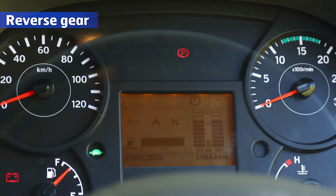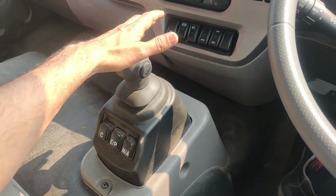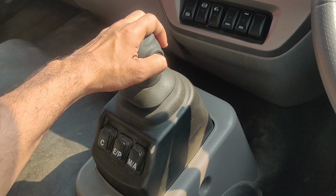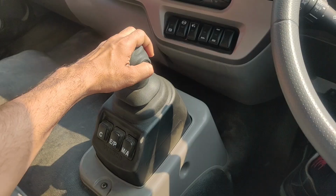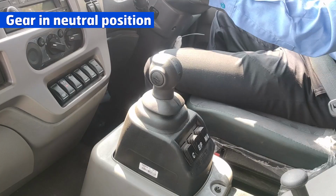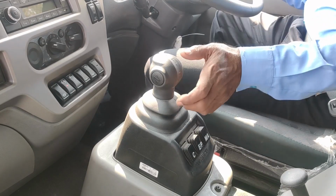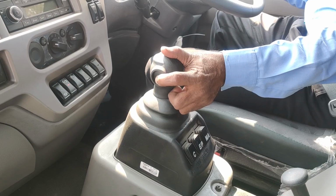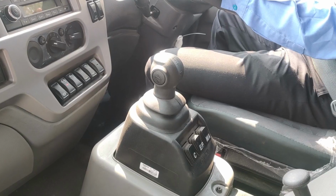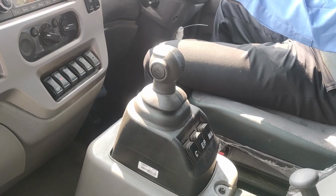Reverse gear. When the gear is in neutral, reverse gear is requested by pressing the function button of the shift lever unit and simultaneously moving the shift lever backward. Gear in neutral position. A shift to neutral is requested by pressing the neutral button while the function button remains released and the shift lever is in the middle position.